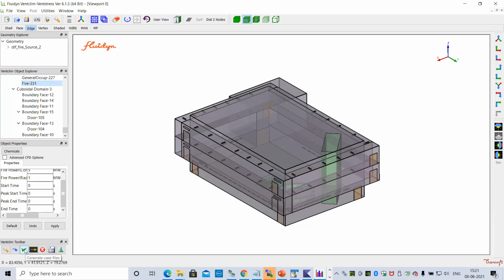Basically, whenever we click this option, according to the obstacle information, it will collect the important places where we want to define the mesh, so that later it can create a group and define conditions there. Other than that, based upon these points, it will create the mesh, group it based upon these definitions, and assign conditions. Finally, all assigned conditions will be written in an INP file, as a file format for the solver. It will write in the particular location we gave.